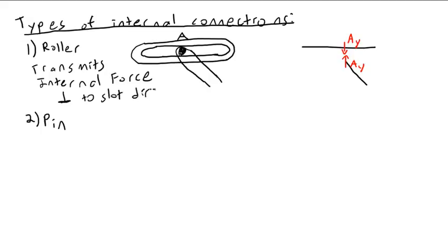Now this one can actually be kind of tricky because, imagine the slot is at an angle, then you'll have an internal reaction force that's at an angle, and it can get a little fun to calculate that. A pin connection transmits X and Y internal force.